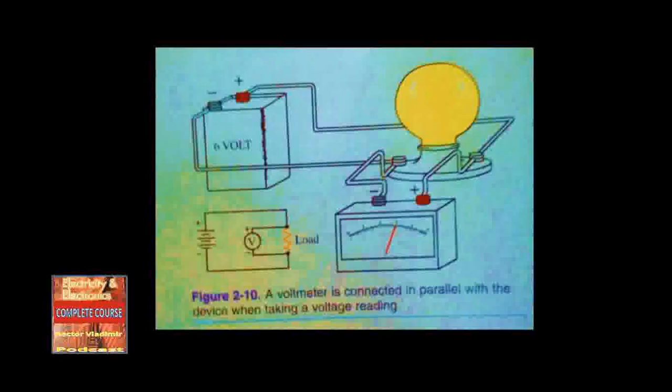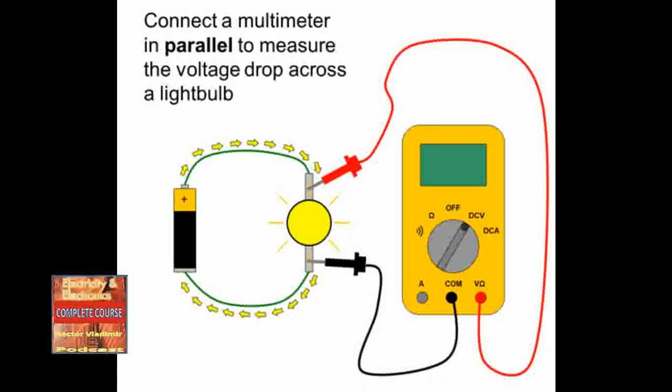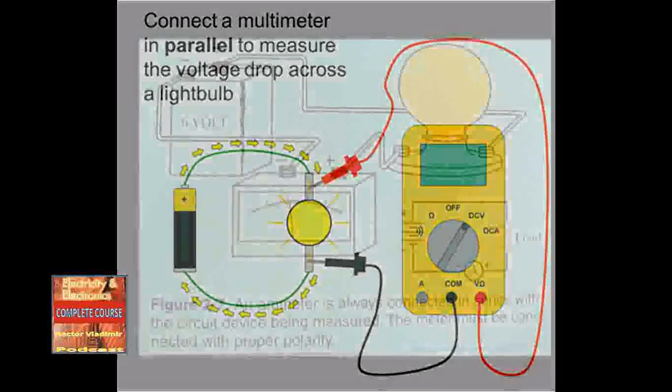When measuring voltage, the meter must be connected in parallel to the device being read. Start on the highest range when measuring an unknown voltage and move slowly to a lower range for increased accuracy as needed. Remember to observe correct polarity. The red or positive lead goes to the positive side of the circuit. The black or negative lead goes to the negative side of the circuit.